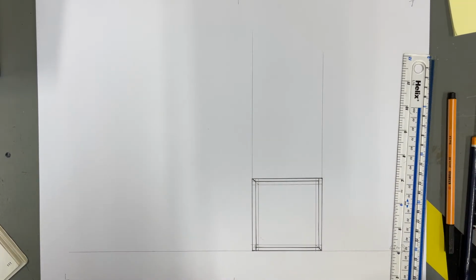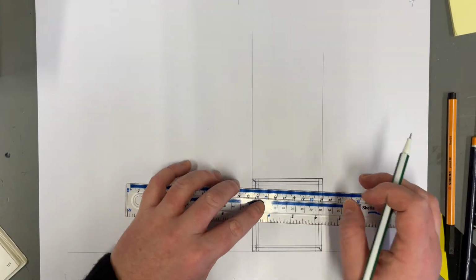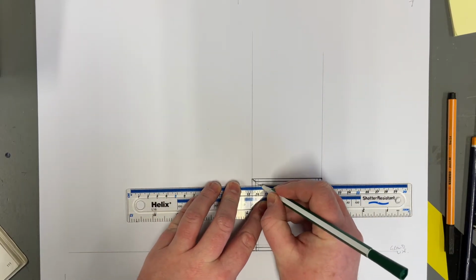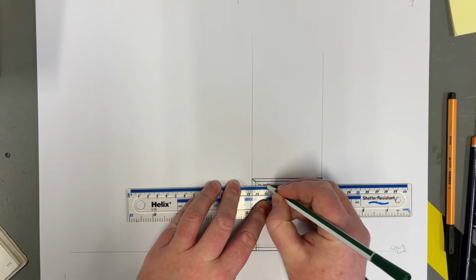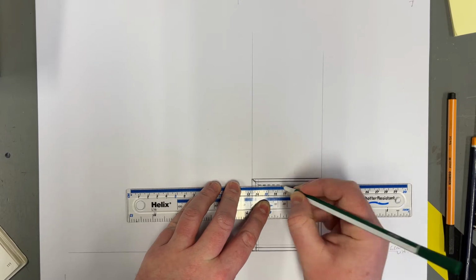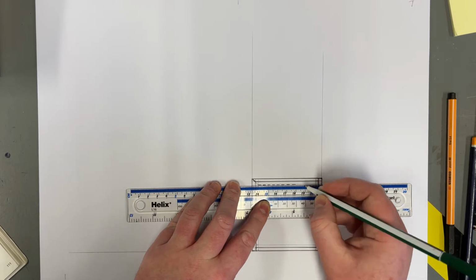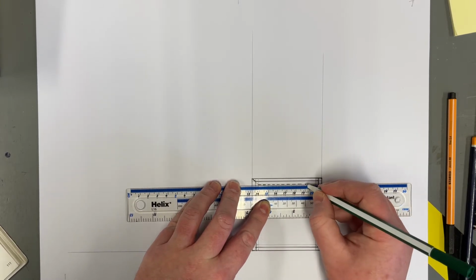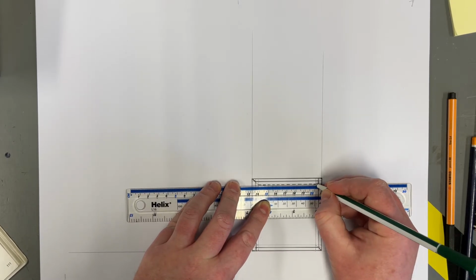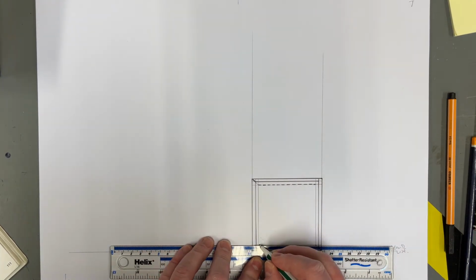But I'm going to do it in a green pen just to make it clear for you on screen. You wouldn't need to do that. Just a little bit heavier, but a hidden detail line is a short dash with an even shorter gap in between. Now, if you remember back to first year when I was teaching you this, or if you do Graph Com, technically a hidden detail line, the dash should be about 3 millimeters with about a 2 millimeter gap. But this isn't graphics, this is D&M. It doesn't need to be as accurate and perfect as that. Certainly not when you're doing a sketch. Okay.